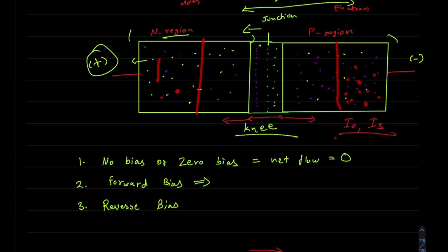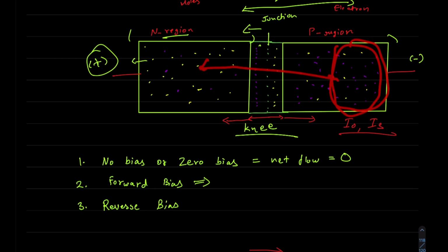If the energy is enough to kick electrons out of the valence band or even the lower energy band, they might have enough speed because of the reverse voltage to kick out other electrons as well, and there will be a chain reaction, and billions of electrons will go towards the end region at the same moment.